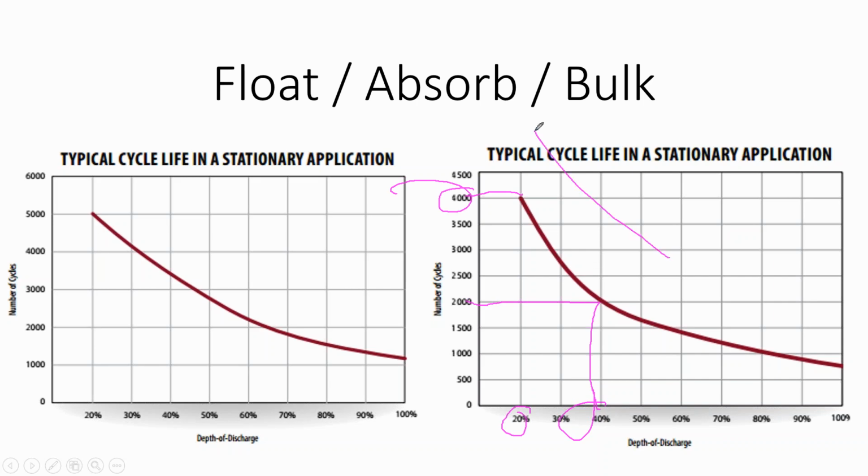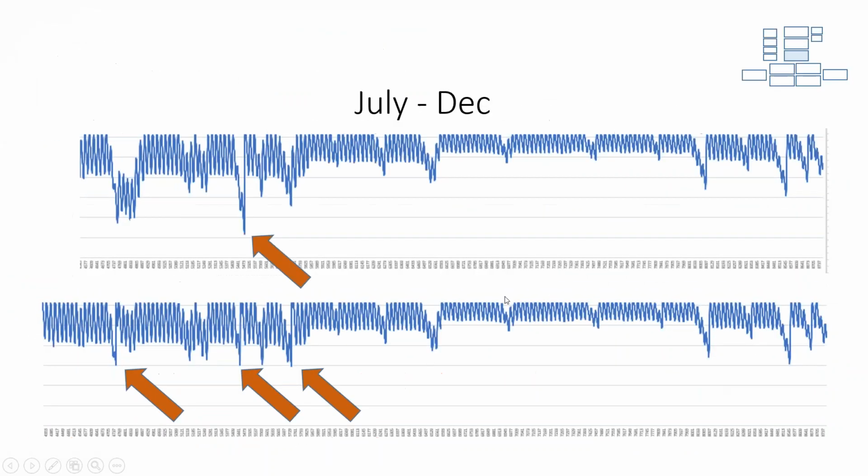So, oversizing the battery is not like solar, where if you oversize the inverter, you're not really using the inverter efficiently. If you oversize a battery bank, you get more life and value out of it. If you undersize the battery bank, then you're getting down into this bulk phase that is more damaging for the battery. So it's worse to undersize the battery than oversize it.